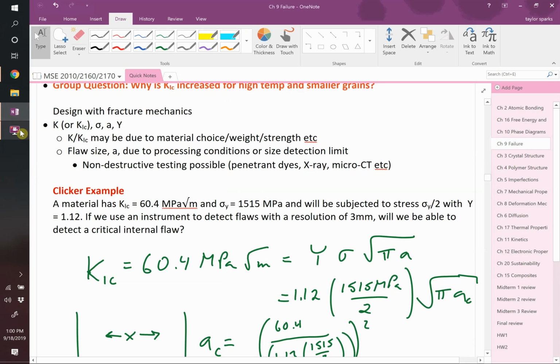So that's X-ray. You can also do it with ultrasound, which basically takes a pulse of sound, right? It takes vibrations. It passes them through the material, and if it hits a defect, it'll bounce back to the receiver faster than if it were to travel all the way through the material, right? That would bounce back later, and so they can actually detect flaws in material.